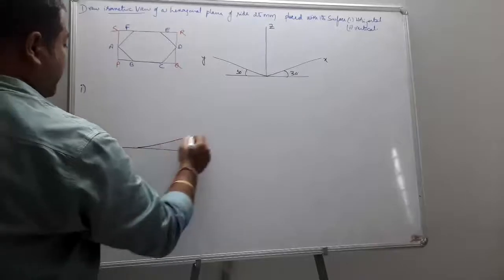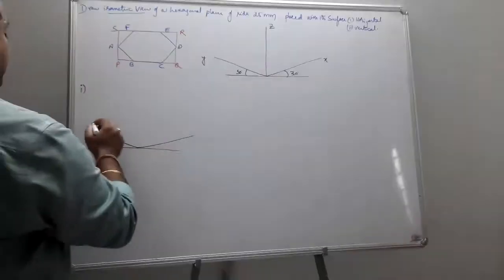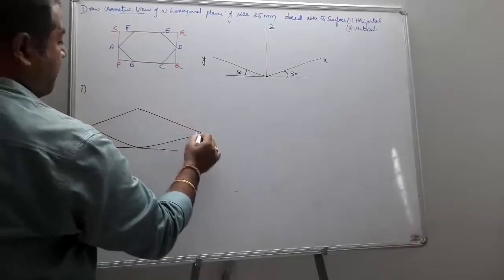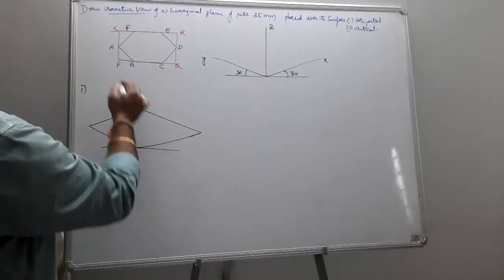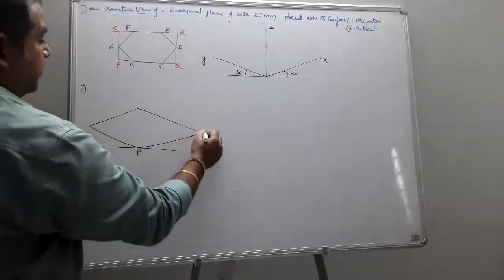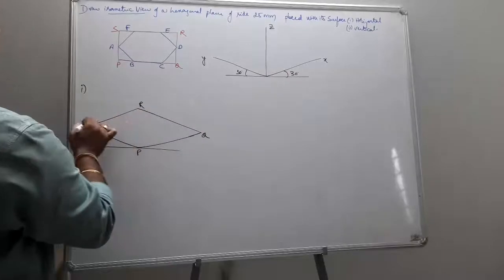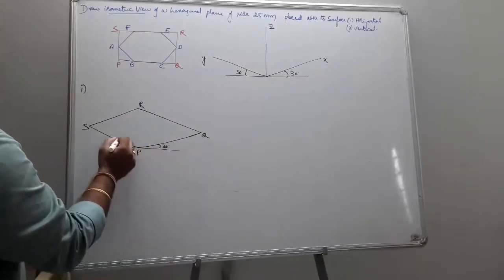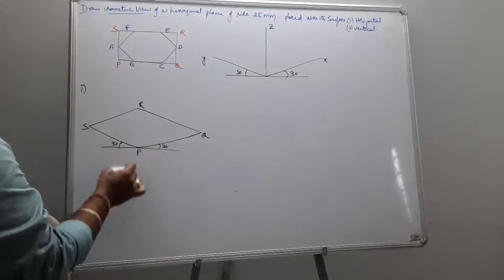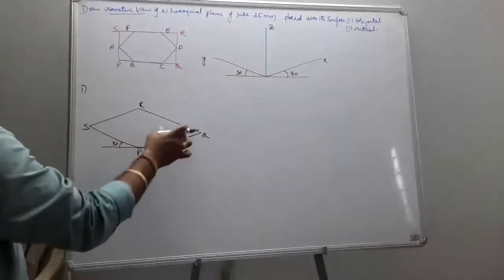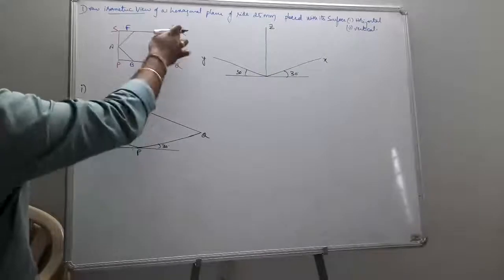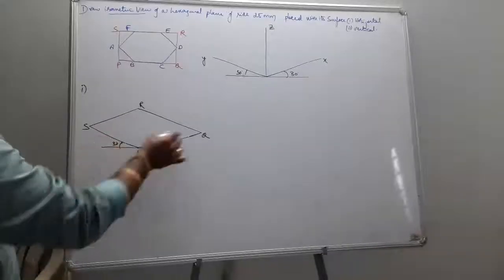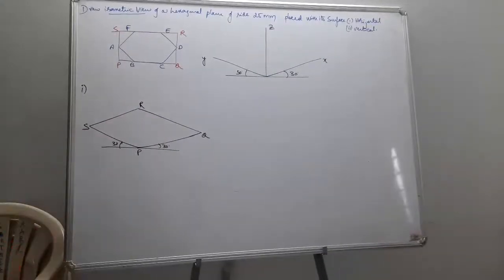So further I just draw my X and Y. So this is your box PQRS. You just draw lines at 30 degrees and 30 degrees to here. Mark it as point P. From P, I draw Q, draw R, draw S, and you join to obtain a box.